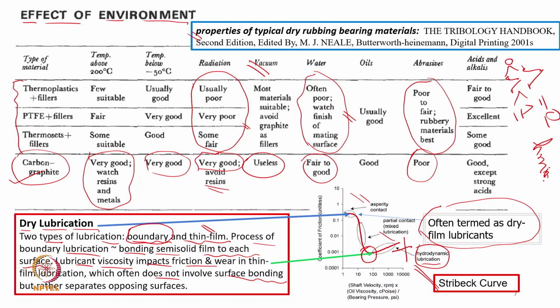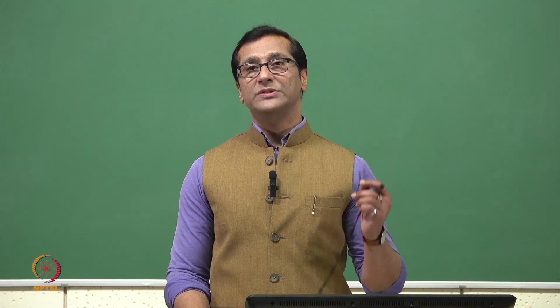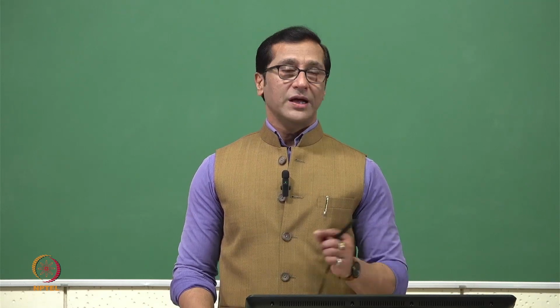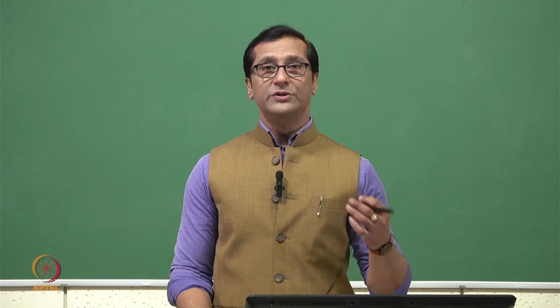what is the meaning of this? If I'm assuming everything, we say the RMS of surface 1 and the RMS of surface 2, right? So in this situation, what is the meaning of h minimum? For solid lubricant, if I am depositing a few microns, and we know the surface roughness can be calculated, I can calculate this specific film thickness even for the solid lubricant, because we are going to deposit the coating or the film. Naturally two surfaces are getting separated, and this reduces the wear to a low level.